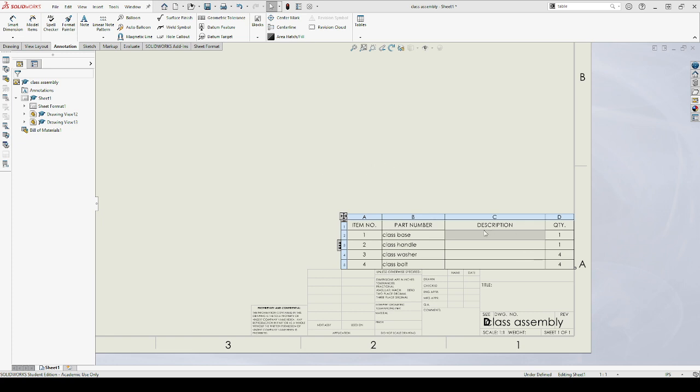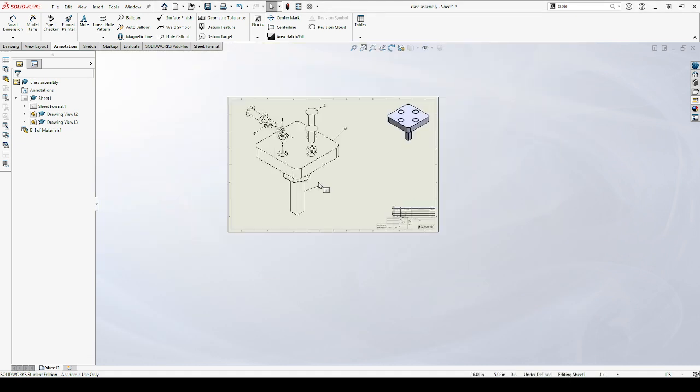Oh, okay. So yeah, you can always add a description to the part itself, or we can do what they call break link, and then it'll detach itself from the part, so that way you can actually do it. I recommend just keeping the link and adding in the description the way you can over on the model side. So I'll hit cancel there.